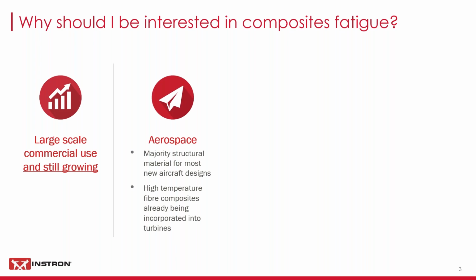So who are those people who want that data? First and foremost, I think a lot of you will be very aware of how much importance the aerospace sector puts on composite materials, and really the majority of new commercial, well, also military aircraft. All major aerospace is pushing to have a very large proportion of composite materials in new aircraft designs. You should also be aware that, in a slightly more futuristic sense, you've now got high temperature composites, so things like carbon-carbon composites are already being adopted into turbine designs. And that's something that's happened a lot more quietly, I think.